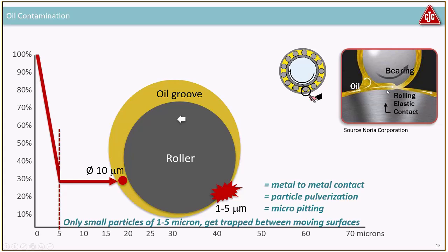It's called elastohydrodynamic lubrication. So the bearing is actually elastic because of the so high pressure. It's more than 35,000 bar, which I believe is something like, what is that in PSI, 150,000 maybe, something like that. Very, very, very high pressure. So you're actually deforming the ball and the racetrack. Of course a sand particle is very easily being crushed, but sand is harder than steel, even hardened steel. So dust in the air or sand will easily destroy my surface.